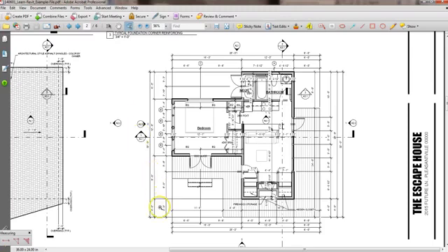So if you always fill out all of your dimension lines from beginning to end, no matter what, and if you always do the 3 tiers, and always do it on all 4 sides... some people for some reason will want to just do 2 sides and then 1 tier on another side. It doesn't take you that long. It's not that hard. Do 3 tiers, all 4 sides, all the time. That's it. That's simple. And your plans will become clean, and everyone will know how to find dimensions, and it'll be pretty simple.